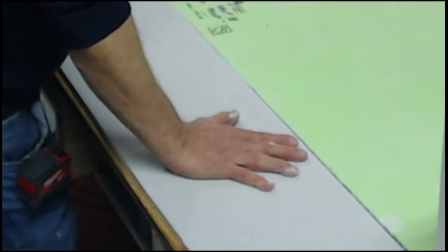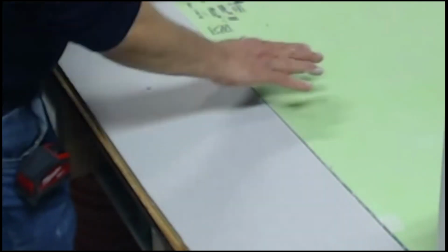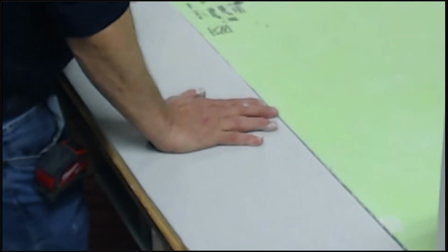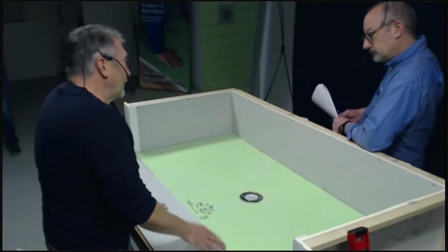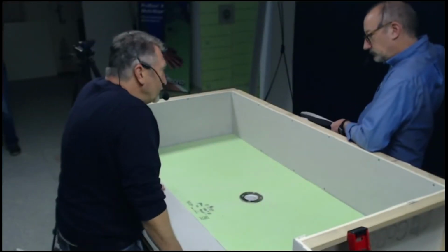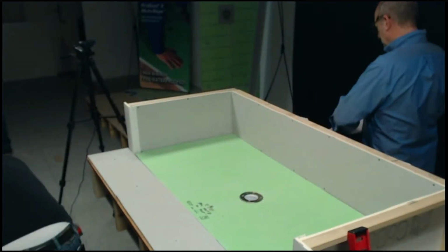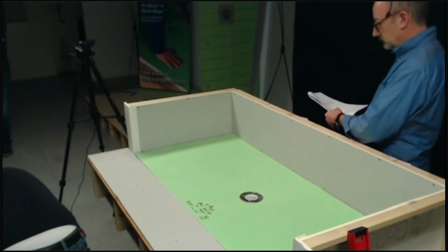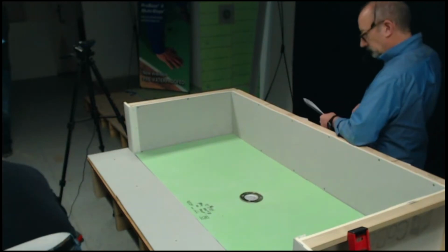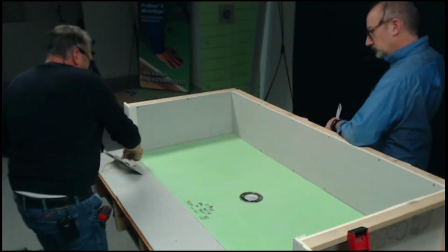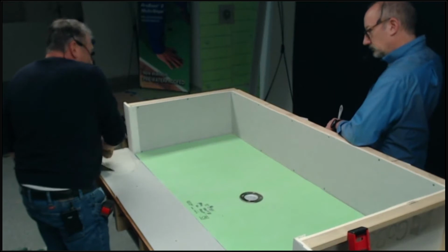So now I have my basin, I have my dry space, and a nice transition to this. I'm ready for my waterproofing to my dry space and all my upturns for my base. On my dry space here, again, I'll use my same modified thin set. I'll just put a 1/4 inch or 1/8 inch V-notch trowel, depending on the product.